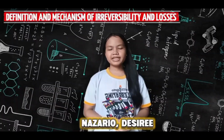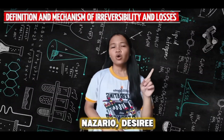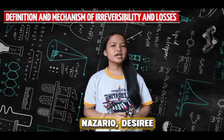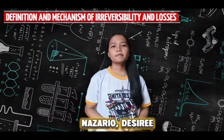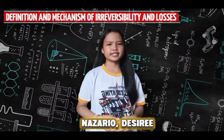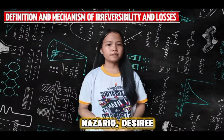In short, irreversibility is the one-way nature of processes that permanently generate molecular disorder, or entropy, and prevent a system from returning to its original state without external energy, while losses represent the specific portion of high-quality, useful energy that gets permanently degraded into chaotic, low-quality heat due to irreversible mechanisms like friction, turbulence, and rapid temperature drops. Remember, you cannot destroy energy, but you can destroy its usefulness. Wherever a process is irreversible, a portion of your high-quality energy degrades into low-quality environmental heat, leaving you with permanent thermodynamic losses.